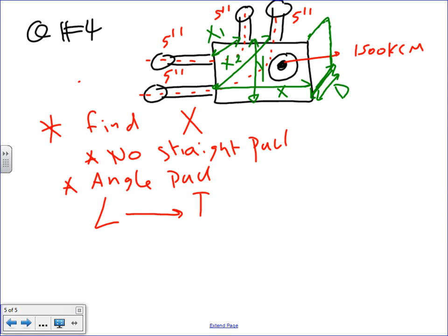Okay, you take the largest conduit engaged. Which one is the largest conduit engaged? Both of them are engaged and both of them are 5. If one of them was 5 and the other one was 6, which one would you use? The largest conduit engaged, so that would be 6. From this calculation, you're going to find 6 times 5 plus 5, right? 6 times the largest conduit engaged plus all the other conduits sharing the same wall. Looking right here, that will be 35 inches.